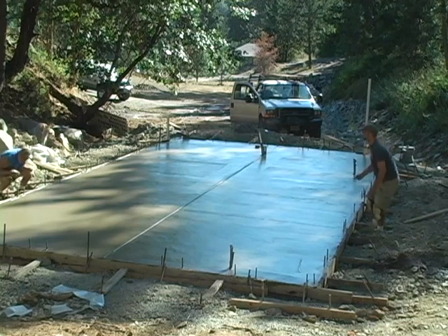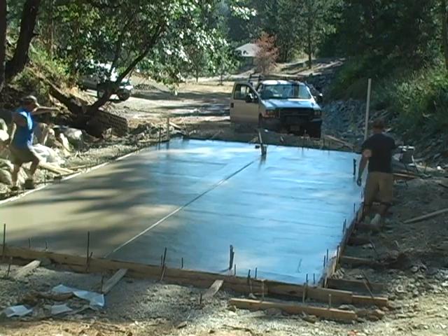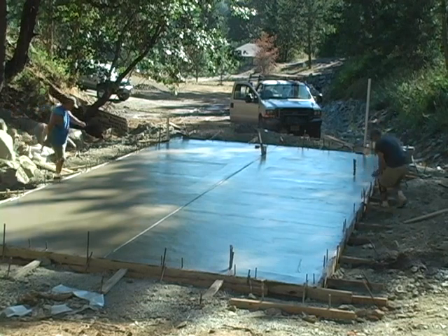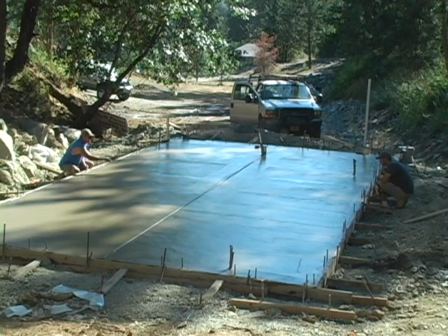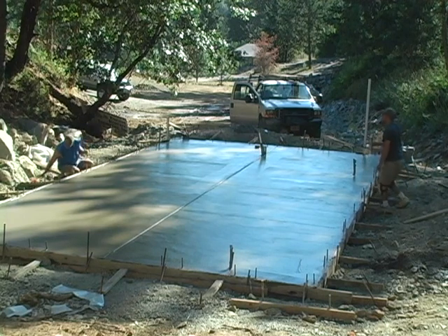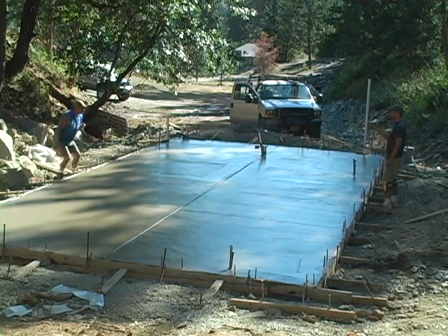So here we're snapping lines. We're going to run some perpendicular grooves to our main groove. So we've got them marked out on the side of the foam board exactly where we want to have these grooves in place. And in general, you want to keep them about 6 inches away from any wall that they're going to be running parallel with.